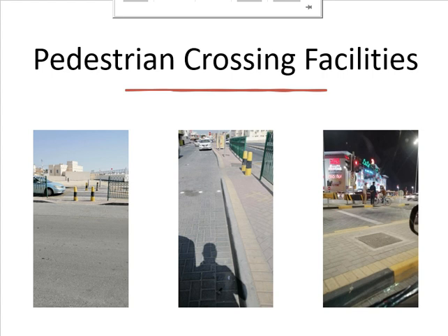For drivers, we have two important characteristics: visual acuity and the perception reaction process. For visual acuity, we looked at different functions performed by the eyes during driving, and we also looked at different fields of vision. For the perception reaction process, we measure it in terms of time, and that time depends upon the expectancy of the situation. Unexpected needs more time, and vice versa.